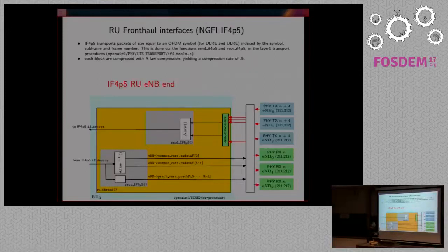In a system like 4G, on the receive path, the terminal can transmit the normal uplink signal and control channels, or it can transmit the random access signal. Those are two different kinds of signals. So you actually need two kinds of packets to encode those signals, and two different types of processing when you receive them. Again, the data signal part is compressed and the other part is not.